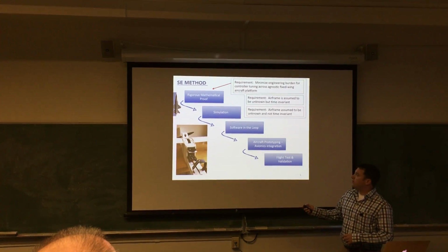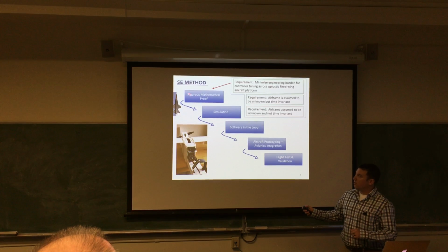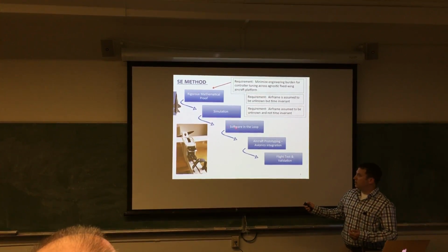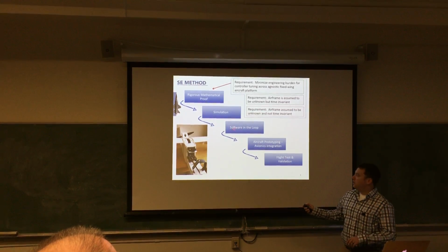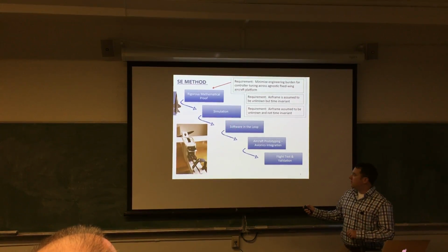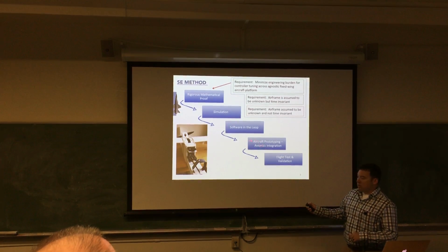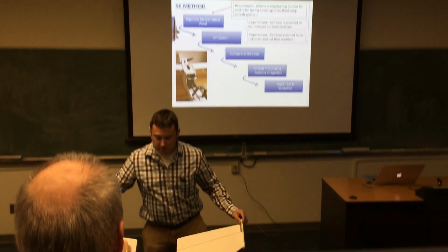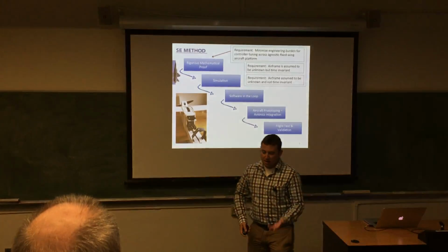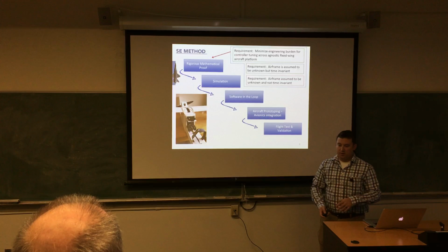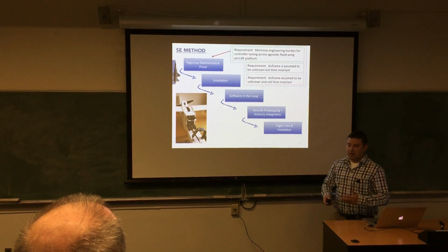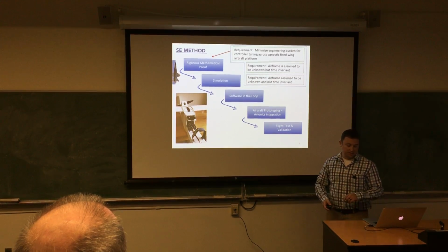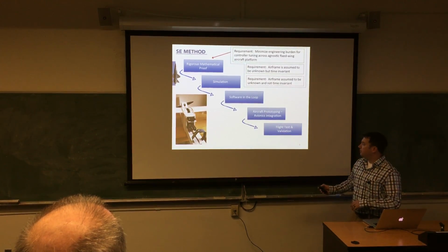So this is the process I walked through. I looked at some conventional controls and ultimately ended up choosing one of them. I put it in simulation, software in the loop, to test it on the actual autopilot in simulation using X-Plane and things like that. Then I prototyped an aircraft, and I brought one to show you, the scale of an airframe that I was working on, something about that size. It's about $4 of Dollar Tree foam board. It's really cheap and easy to manufacture. I could produce one in about a day, so it didn't really hinder my actual research, which was testing the algorithm.